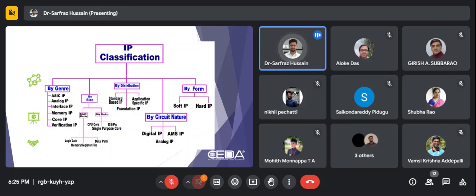In the soft and hard IP, in the soft IP, basically we have Verilog code or VHDL code. With this Verilog and VHDL code, we just call upon the XOR or AND gates. These are called soft IPs. Now for the hard IP, when we do it manually, if we have a layout of an AND gate or a layout of an XOR gate and directly use that layout, that is called the hard IP, meaning we do it manually. Whereas a soft IP is already predefined and we just follow it with the help of a program.